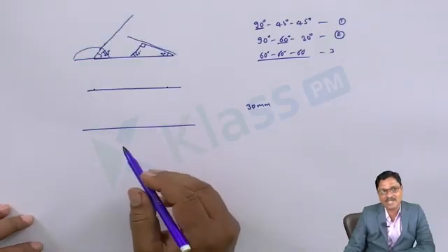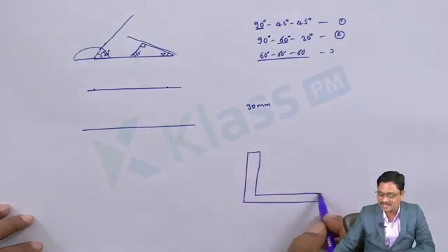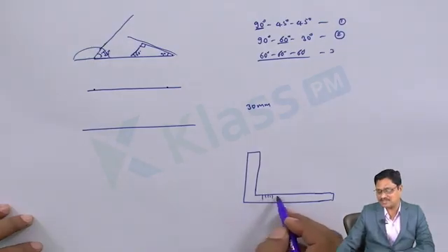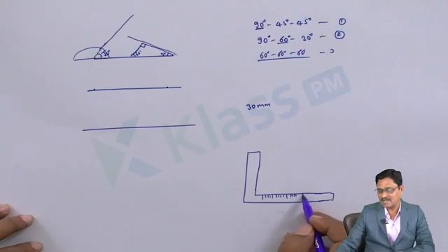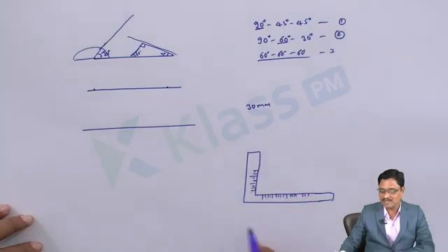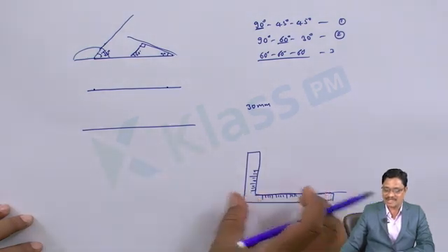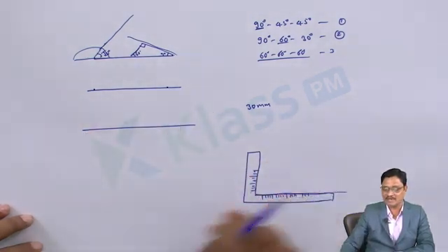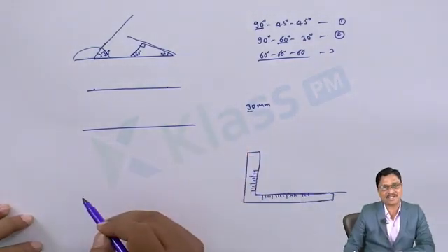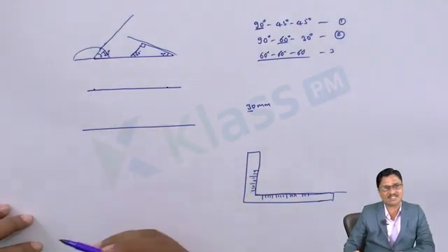Instead of that, if I use the mini drafter, I am talking only about the scale part of the mini drafter itself. So already we checked the gradations, horizontal as well as vertical. Now this is the line we are getting. Assume this is the line, and I have moved this so that they are coincident. What I need is a parallel line at a distance of 30 mm, so I have to measure perpendicularly from the existing line with 30 mm, as you just checked.